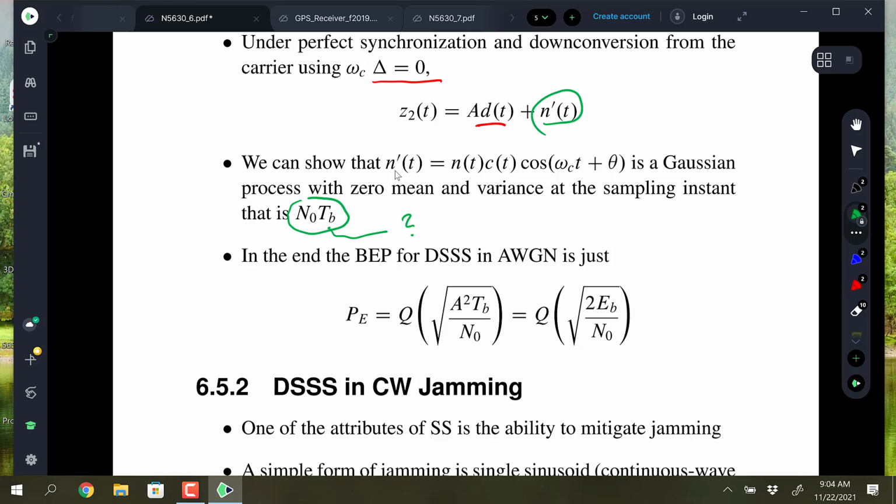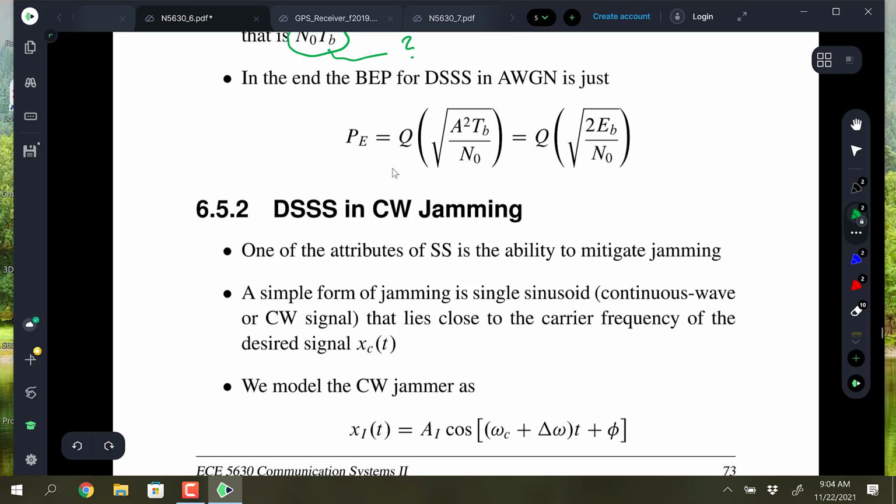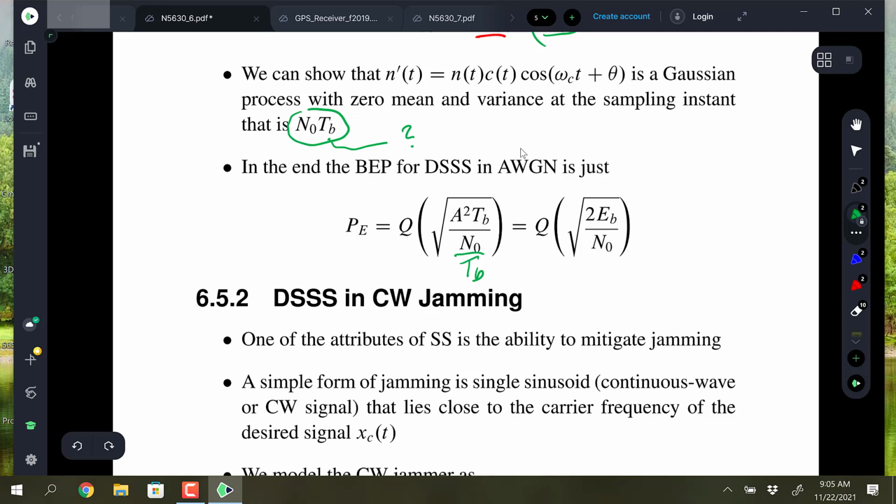I have to think about that right now, but it is a spectral density, noise spectral density, and so the direct sequence spread spectrum signal doesn't really modify the additive white Gaussian noise. It's already white noise, and multiplying it by a spreading code doesn't really spread it out or collapse it down. It just kind of makes it look the same. And so the error probability is the same. But now we've pulled the signal up, that's when it's despread. So maybe that's why I had the Tb in there. But I don't think so, because A squared Tb would be there already from the energy detecting of the matched filter. So as I'm thinking about this, I think that's not supposed to be there. But I can go back and look in the book, because I know he talks about it in the book.